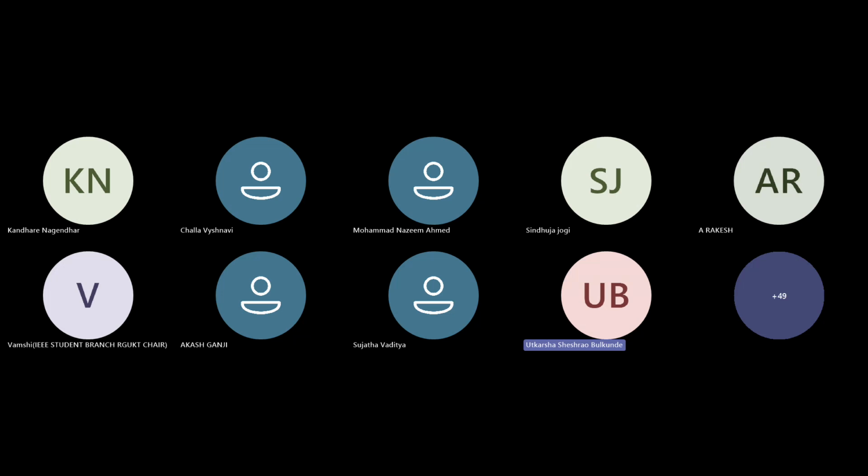So we were here, right? Then in loss model, you have to select power ferrite. Here, Cm is the value of K, which is 12, which we calculated from datasheet only. X is 1.3, which is alpha, and Y is 2.55, which is beta.